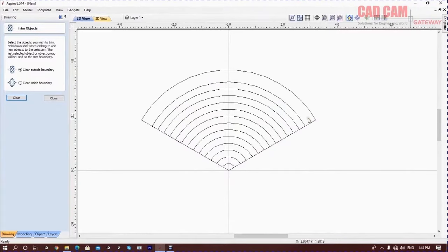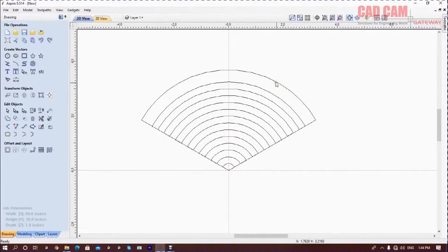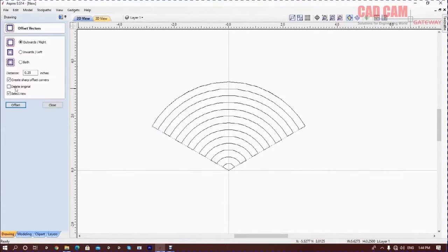You should not remove this. Do not remove the cutting source that we used. Using the node, bring it exactly to this end. Bring it onto this, and then bring it to this end. As soon as you bring it to this position, since we need to create an offset, and the offset is for its boundary, I will create an offset of 0.5 for it. Now you can remove it.